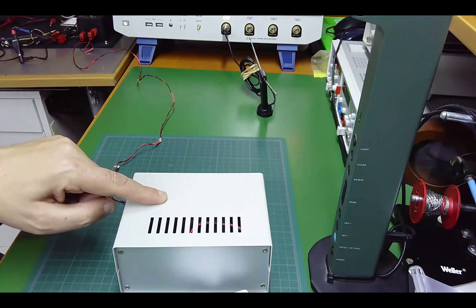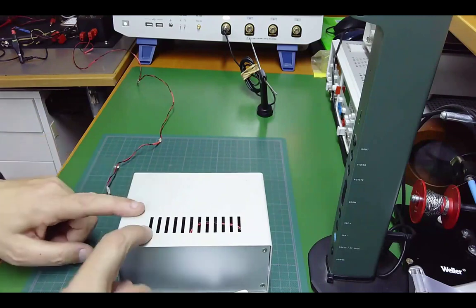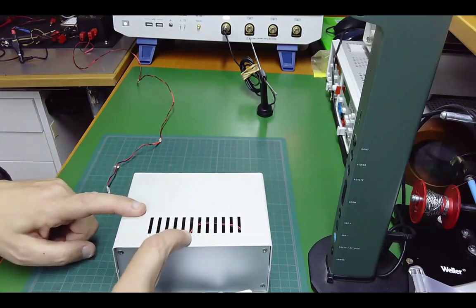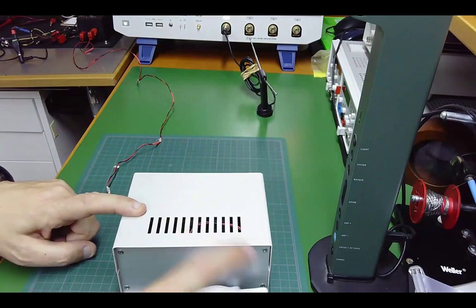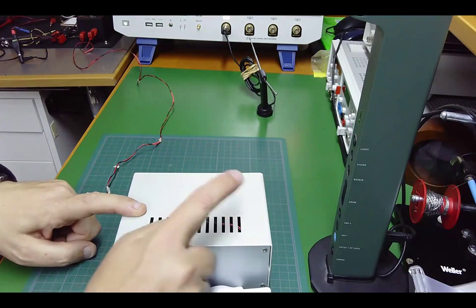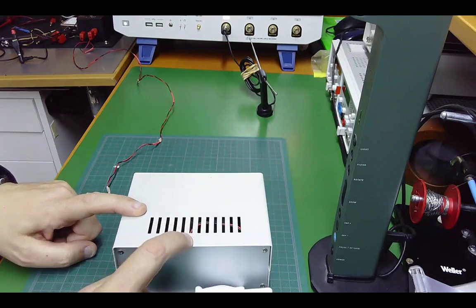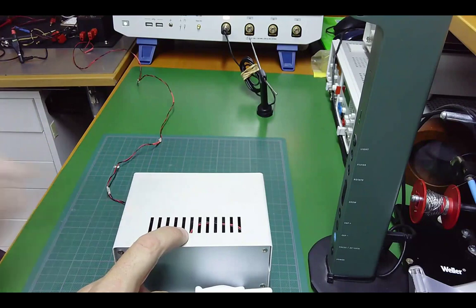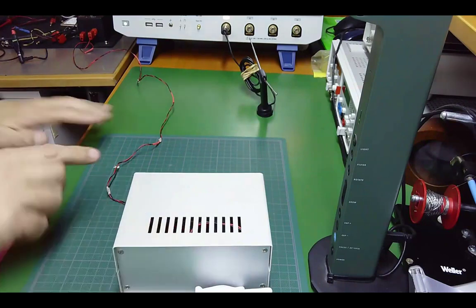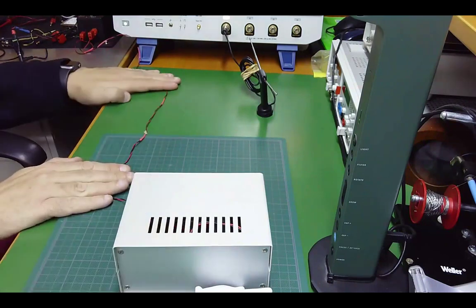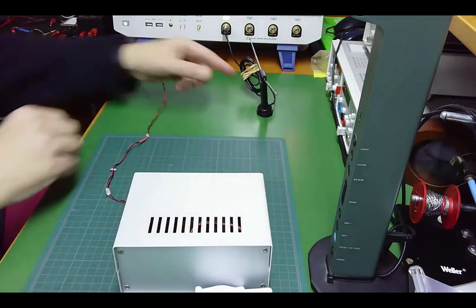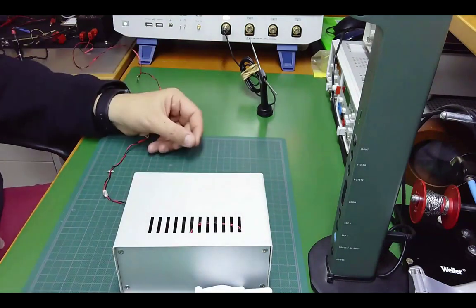If you consider 3 meters, 1.5 meters, you will discover that the slots I have in my enclosure are very small. So it's not easy for these slots or these apertures to radiate a 100, 200 megahertz signal with efficiency. So in this frequency range, usually the problems are coming from cables. Not always, and especially if the antenna is very close to the device under test, like in automotive applications.